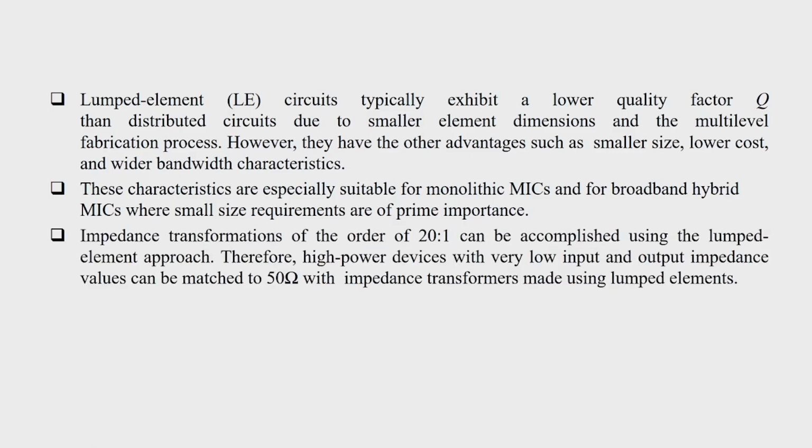These lumped element circuits can provide impedance transformation of the order of 20:1, and therefore, high power devices with very low input or output impedance can be matched to 50 ohm with impedance transformers made using lumped elements.